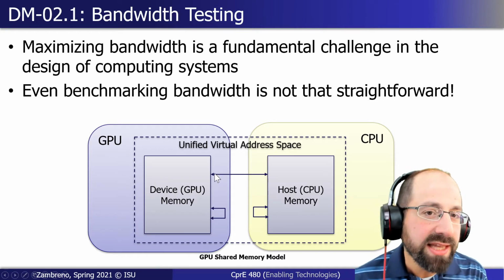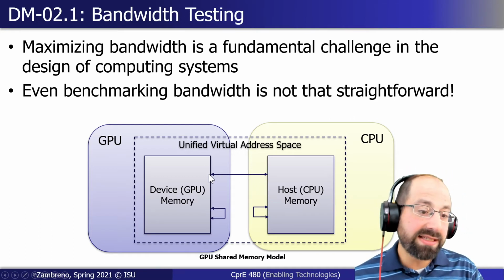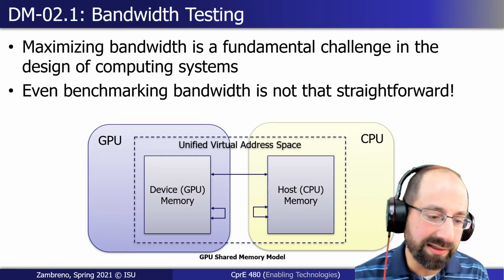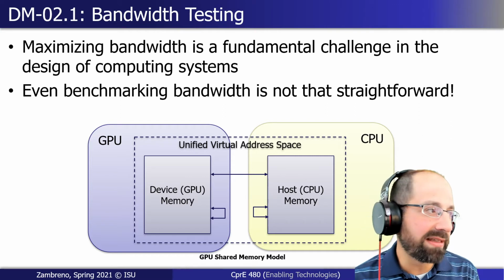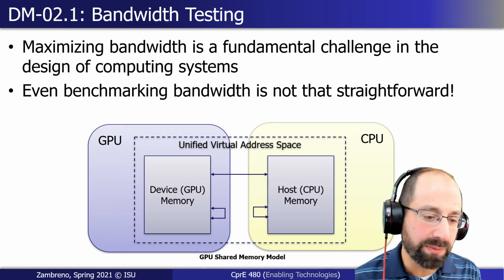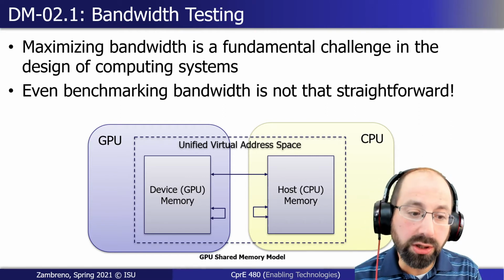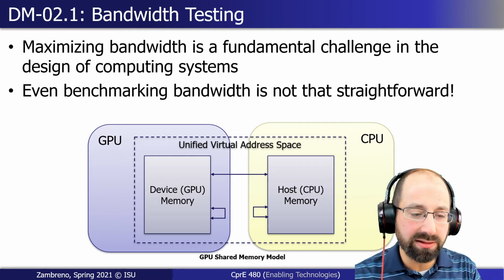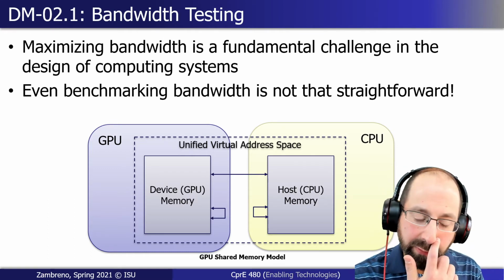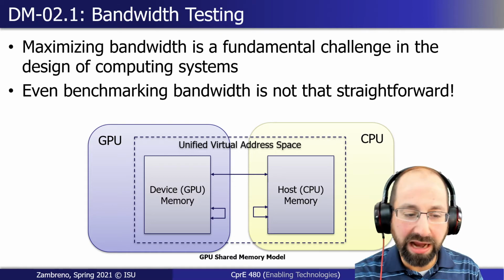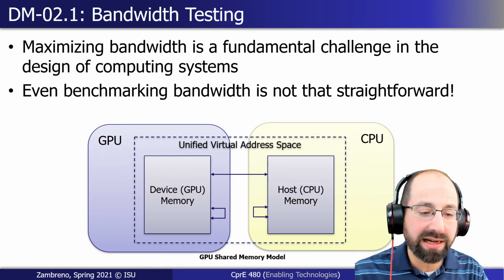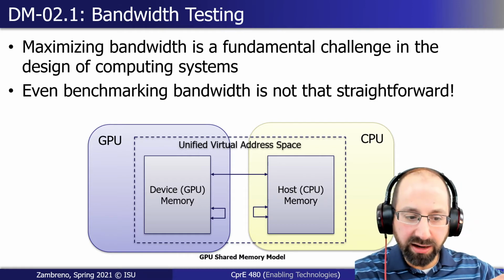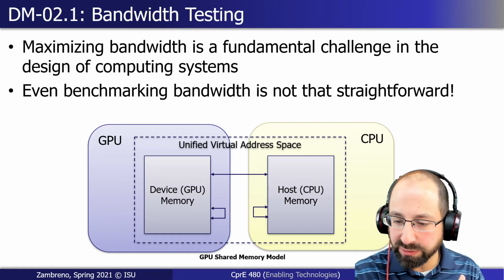Now when we have this arrow here, this is the bandwidth physically between devices. And now you're not looking at DDR bandwidth anymore. You're looking at things like PCI Express bandwidth, which is pretty good still, but because of the fundamental signaling requirements of that type of interface, where I have to be able to plug in a card, and actually run a certain length of cable to have that connection there, it's always going to be significantly less than what your DDR to DDR type transfers can possibly have.